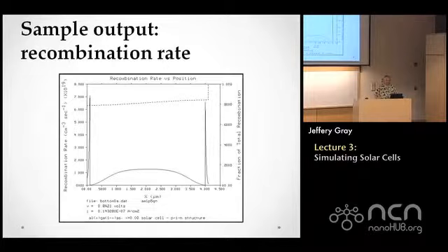You can look internally at the device. What I find the most useful plot is looking at the recombination in the device, because that tells you an awful lot about what's going on. Just as an example, right here you see 2 spikes in the recombination rate, right here and right here. And you might say, in the absence of anything else, that gee, something really bad is going on there in terms of recombination, and this is something I really need to fix.